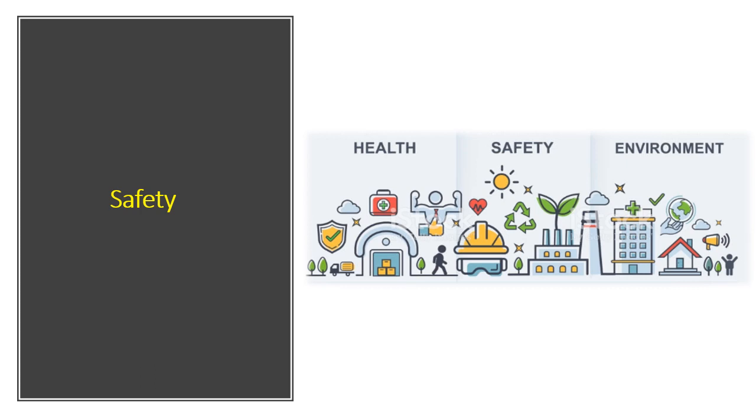So for any industrial engineer, safety is the first priority. Safety involves safety of a man, safety of the equipment, or safety of the environment. For example, a loose coupling or excessively misaligned coupling could be a danger to a man who is working nearby, and a high temperature terminal could be a danger to the motor, which may cause a flashover. A failure of a dust collecting fan could be a danger to the environment, which would cause poisonous or dusty gas to go into the environment.